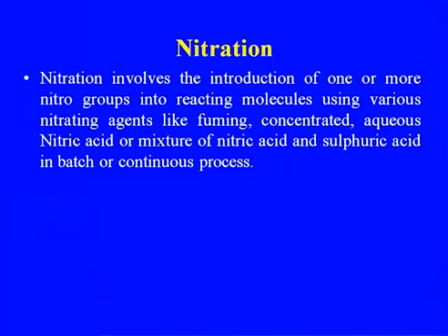Nitration is one of the very important reactions in the chemical process industry. Nitration involves the introduction of one or more nitro groups into reacting molecules using various nitrating agents like fuming, concentrated, or aqueous nitric acid, or a mixture of nitric acid, the mixed acid that we use in the manufacture of TNT, trinitrotoluene. In many other chemical process industries we also use the mixed acid instead of nitric acid. So that is also part of nitration.